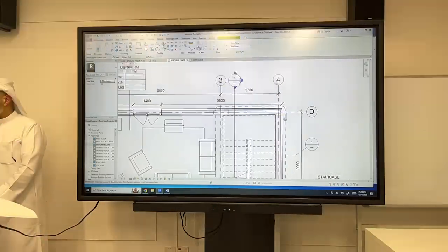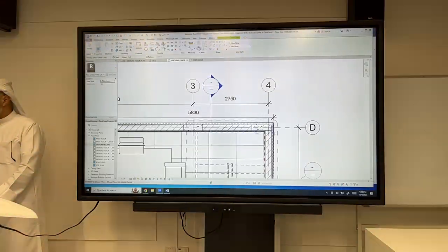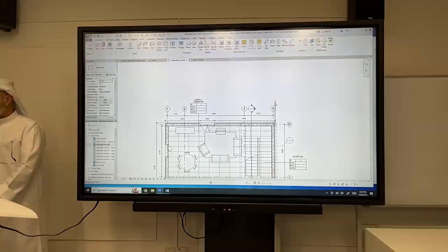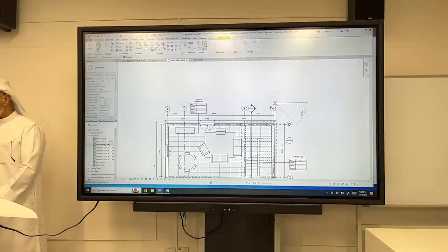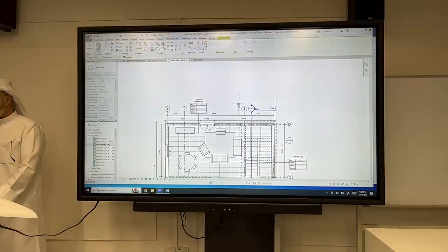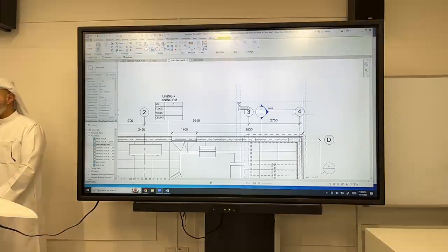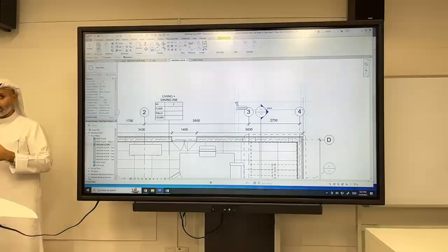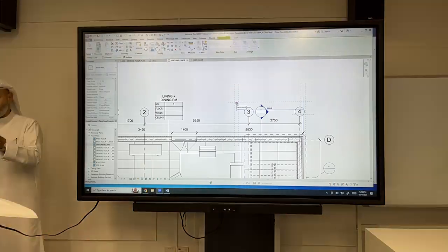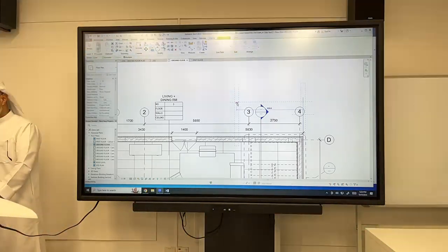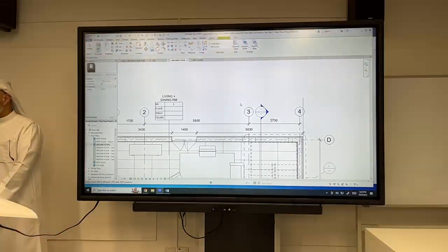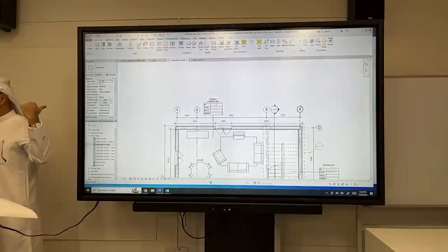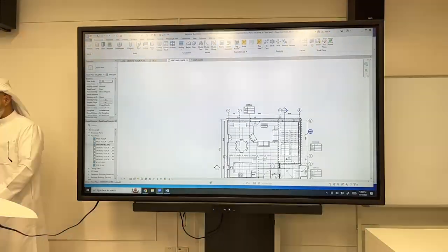So pick the surface edge as your outline. Copy it to a set dimension. Now, for example, look, 3500. Again, it could be every 100 increments or 50 increments. Don't do, for example, 3552. So copy the lines. Always make sure to delete the lines after we finish so they don't stay in the file.